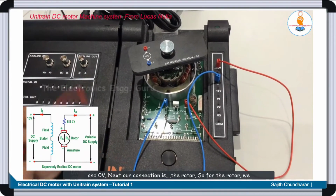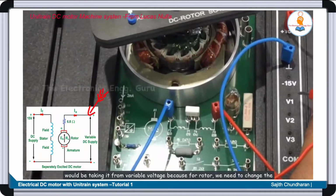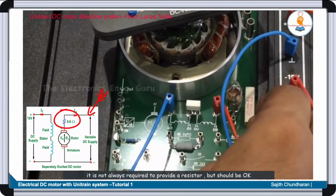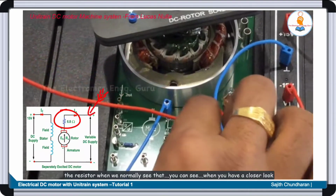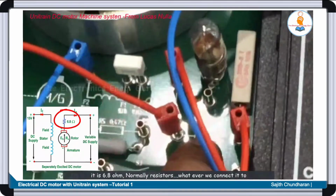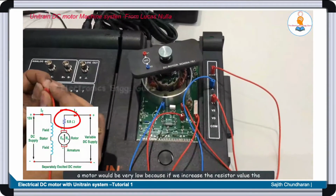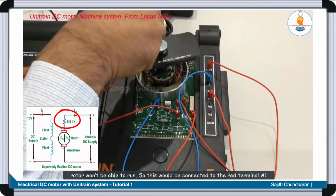Next, our connection is the rotor. So for the rotor, we would be taking it from V2, because for the rotor we need to change the speed. So it is a variable voltage. We would be connecting it through a small resistor. It is not always required to provide a resistor, but it should be okay. The resistor, when you have a closer look, is 6.8 ohm. Normally the resistors whatever we connect to a motor would be very, very low, because if we increase the resistor value, the rotor won't be able to run. So this would be connected to the red terminal, A1 coil.